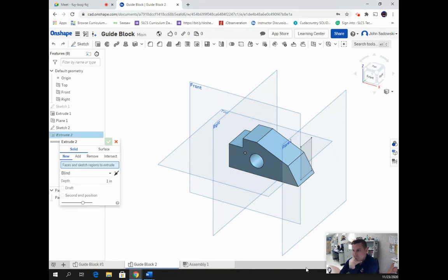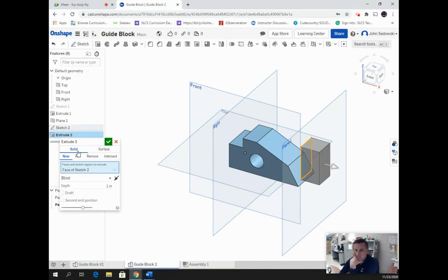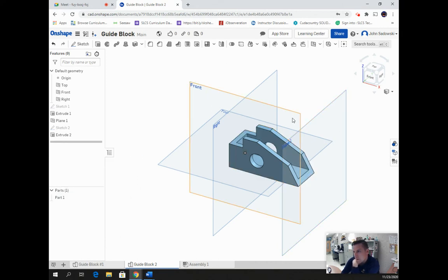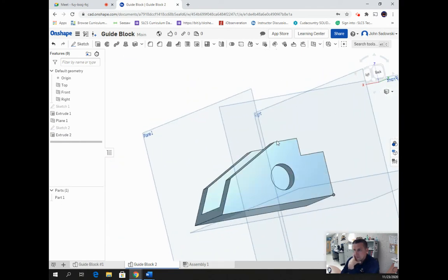So we're going to extrude. I want that shape, but up here I want to remove. So this is going to kick back there. I want it to come all the way back here like this. So I want it to look kind of like that. And doing some little math, it's 3.75, but I still want to maintain that 0.25 thickness back there, so we'll go back 3.5. So now, for all you warriors out there in Bernstein land, that is how that is done.